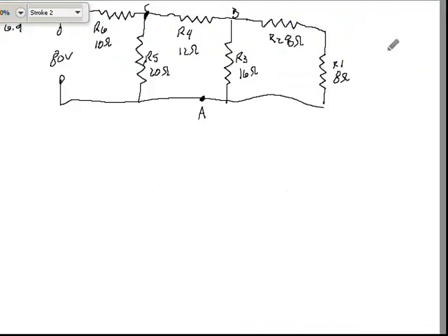Here is about my favorite series parallel circuit to work with. And it looks kind of confusing, but it's a perfect example of the sort of thing you've got to do when you're analyzing these circuits. And basically, you are analyzing the joints and coming up with who's in parallel with who. So I basically just draw it out like a storyline, just straight across, starting with my negative terminal on my source.